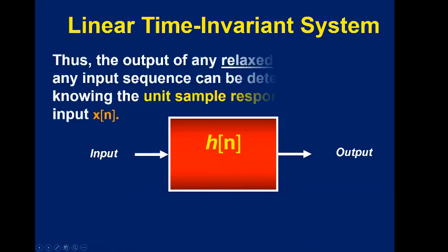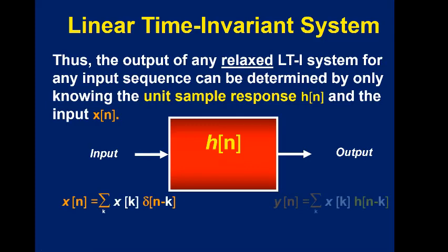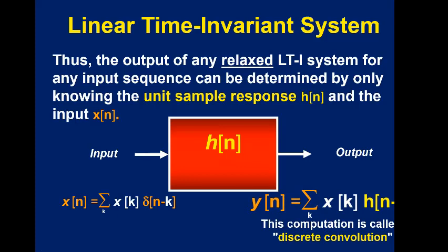It turns out this summation methodology is a perfectly valid way to do it, and a whole technique we're going to learn to use for system analysis. And you'll recognize this as the idea behind convolution, except this is the discrete version of convolution, where instead of nasty integrals, we have simple sums. But the concepts are all the same.